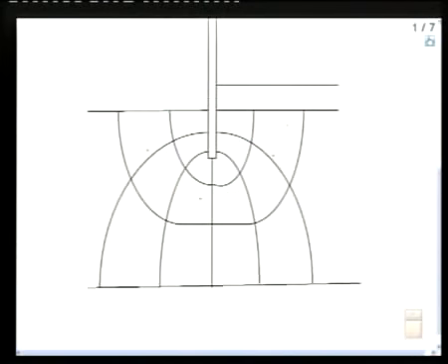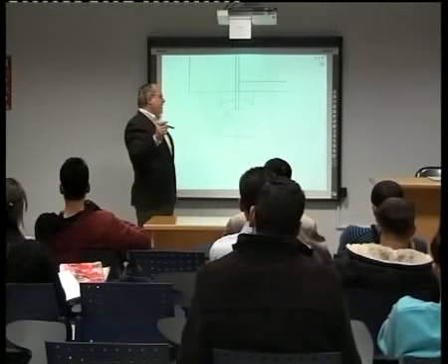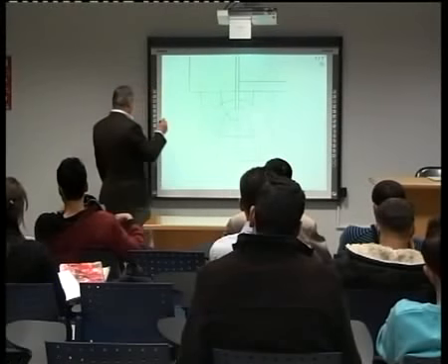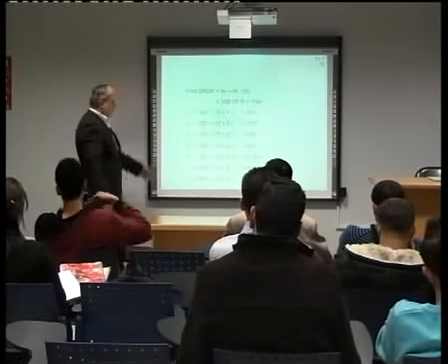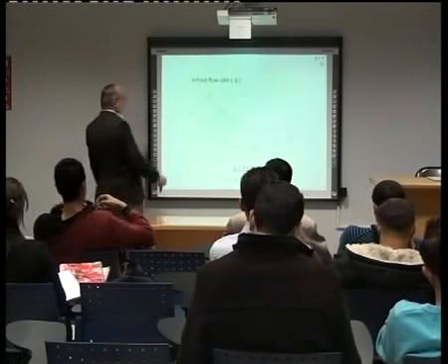What we have to do is just to find what is the height of the water behind the dam, and then subtract from it the drop multiplied by the number of equipotential areas that we passed to reach the point. Okay? We did an example, and I think that you should be familiar with this well. This is the example. I don't want to go through it again.